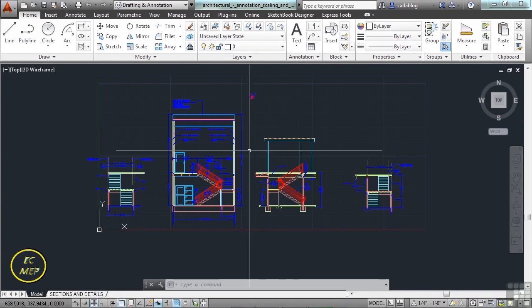Now, one thing that we're going to do is to delete what we don't need anymore, once your drawing is finished. Once an object, a layer, style, or block isn't being used anymore, you can purge them from the file. To do this, type in the word purge.